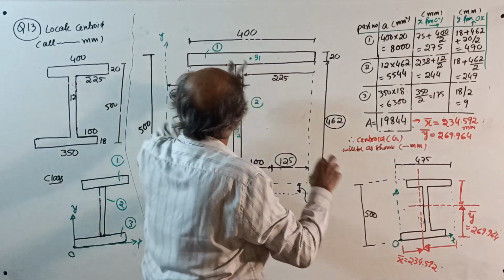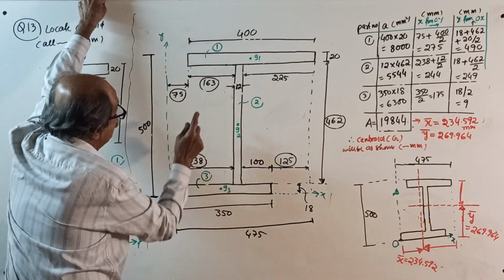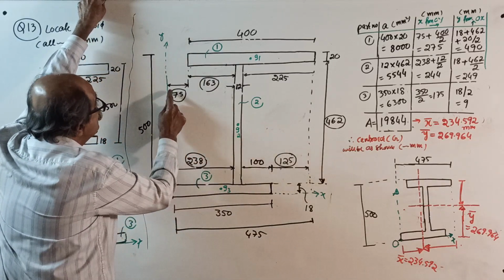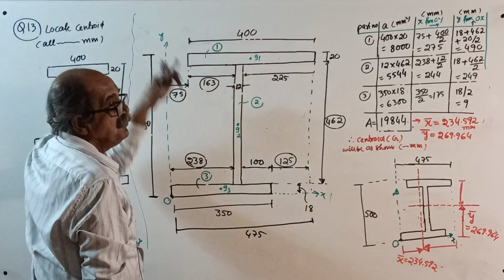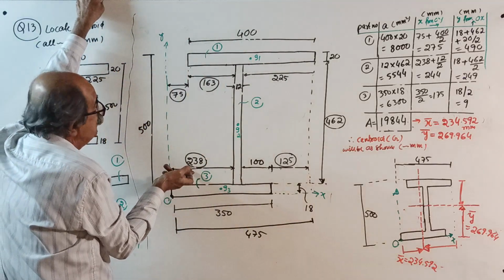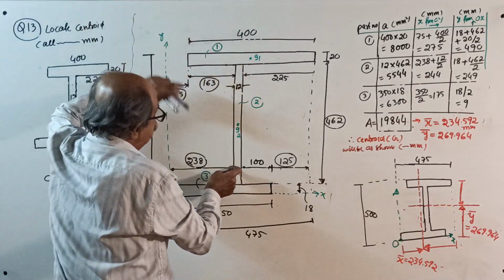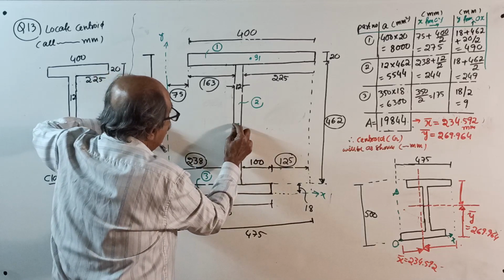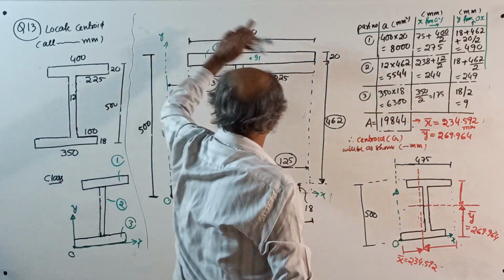Okay, then x2. See, this is 238, here, this centroid, 75 plus 163. Actually, somebody will be laughing. 75 plus 163, visible here 238, don't waste time. So, directly 238, then from here to here, plus midpoint, half of 12, 244.